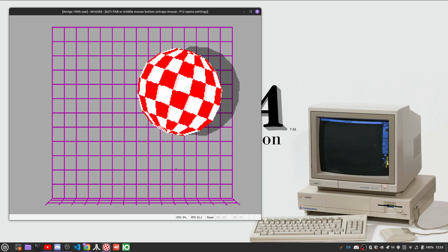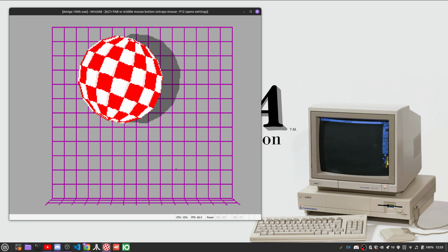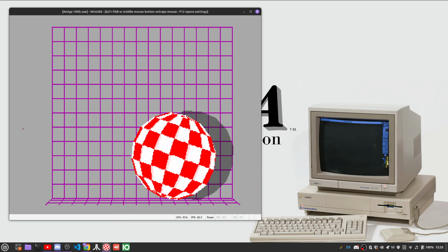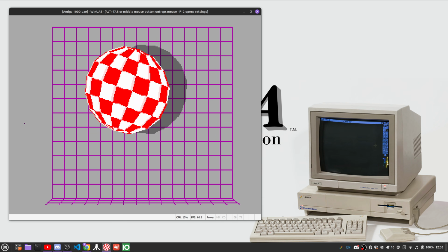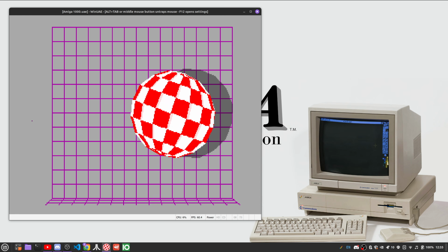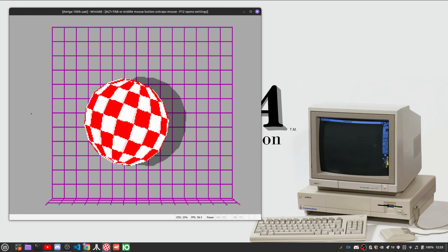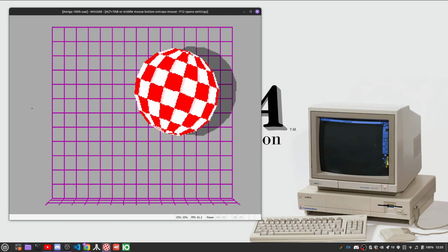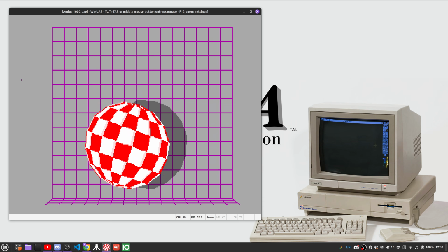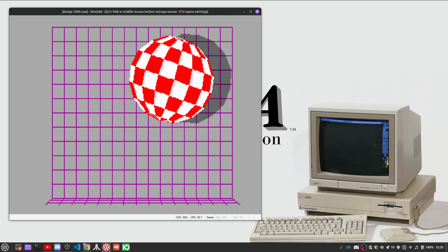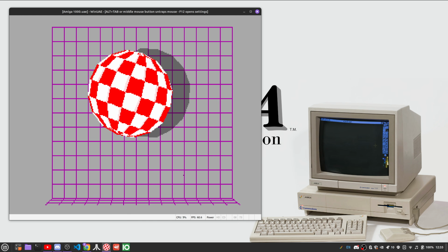The big ball itself is a particular pair of bit planes here, and the position of the ball is literally done by changing the position of where the graphics chips are reading those particular bit planes from memory. Since this is a pointer operation, this happens very quickly. And this is happening while the CPU is, in reality, doing very little here. Again, notice the display here.